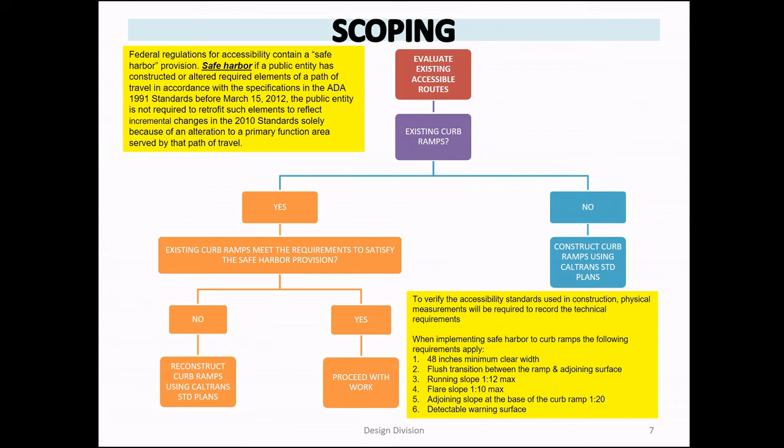There's a few exemptions that I don't want to talk about, but there's areas like in East LA where you have a door right at the back of the curb ramp, and there's no landing because you're not going to create a step. If there's no step, you're not supposed to create a step and make it worse. ADA allows you, but that will be your last resort. ADA allows you for all, even flares and running slope, to be 8.33. But again, we should exhaust everything else before we get to that.